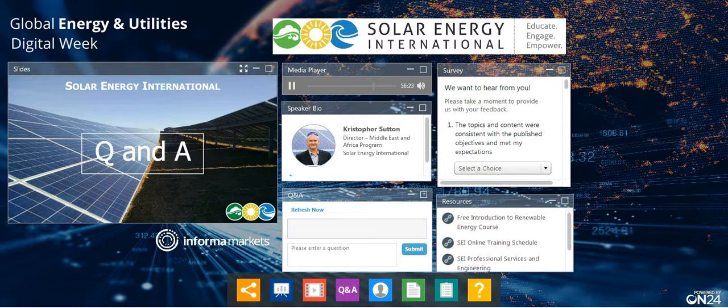What we're doing is we size the inverter based on the size of the solar at that point. So in a grid-connected world, the size of the inverter is based on the size of the solar array. In a battery-based world, the size of the battery-based inverter is based on the size of the load that we're trying to run. Hopefully that's helpful.